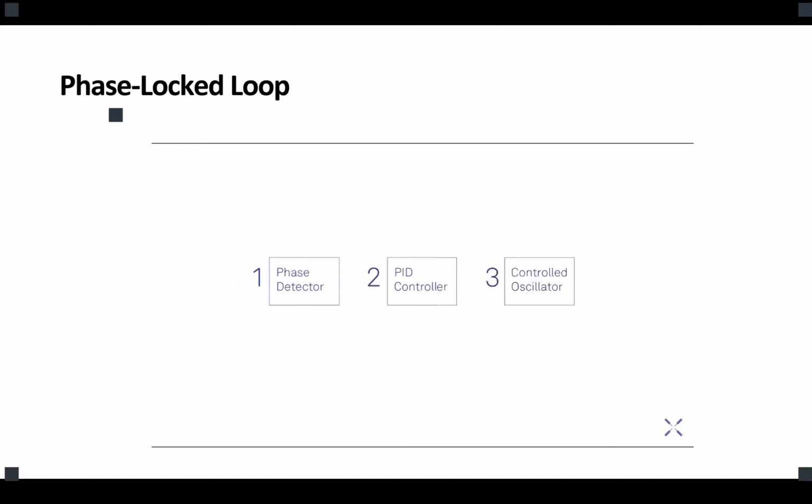Depending on the signals and use cases, different approaches can be used to measure the phase difference between two periodic signals. When using analog signals, a dual phase demodulator, which is the core of the lock-in amplifier, can take a reference signal and an input signal and derive the two quadrature components X and Y. From those, the amplitude and the relative phase can be obtained. The measured phase covers all four quadrants of the whole circle from -180 to +180 degrees.